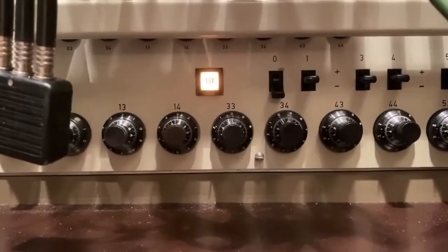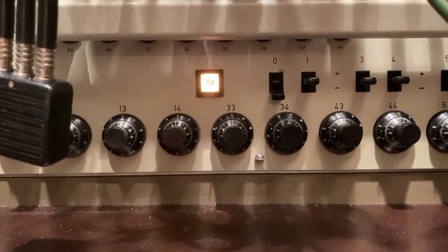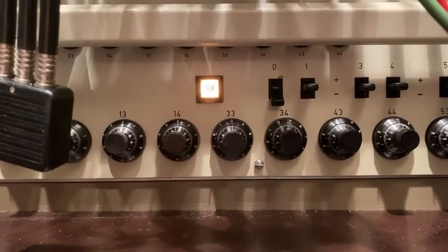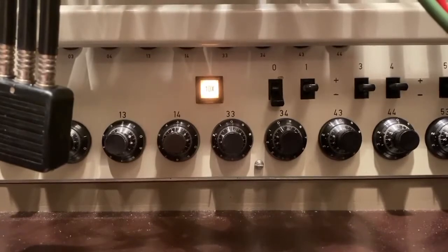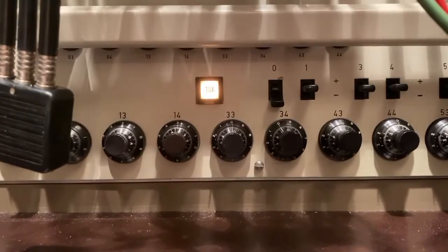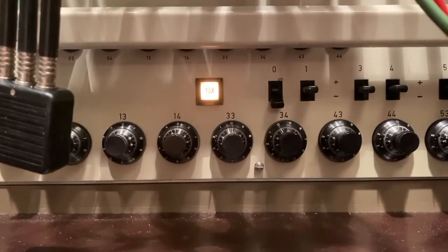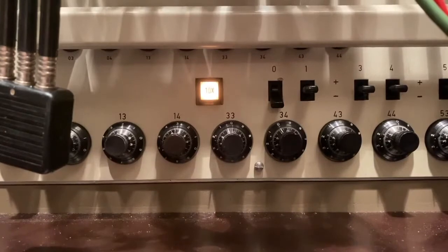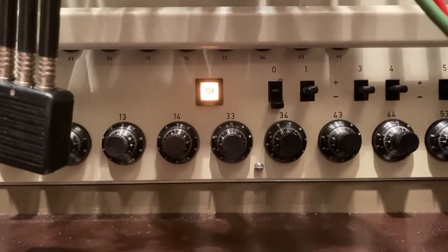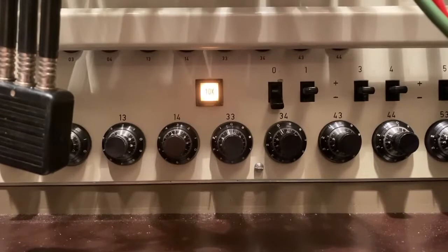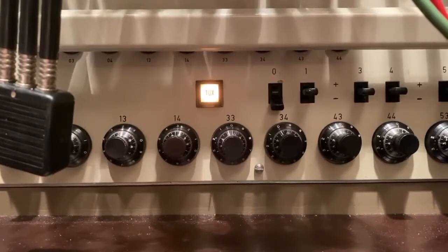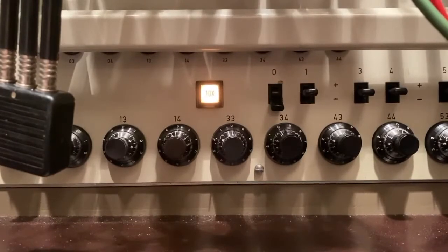Just using these connections, you can select for every integrator a time constant of 1, 10 meaning 10 times faster, or 100 meaning 100 times faster. Large analog computers typically had a special key labeled 10 times, which you can see here. And when you depress this key, this will cause a set of relays to switch all integrating capacitors to another set of capacitors, which is smaller by a factor of 10 than the standard set of capacitors.